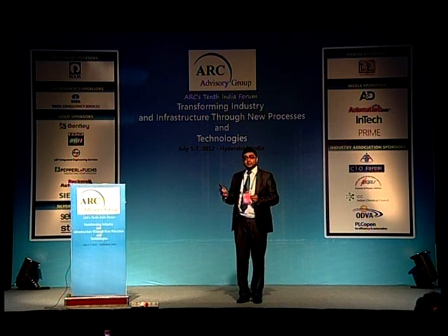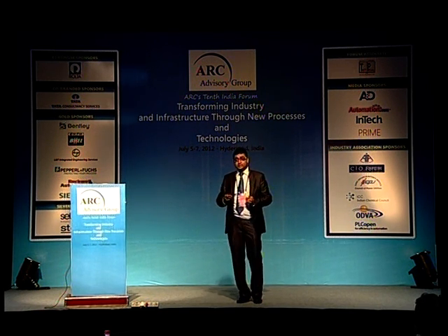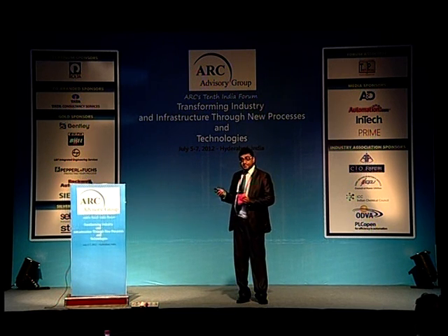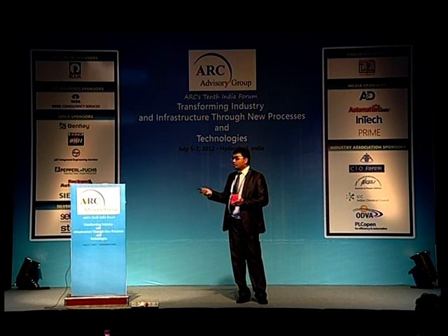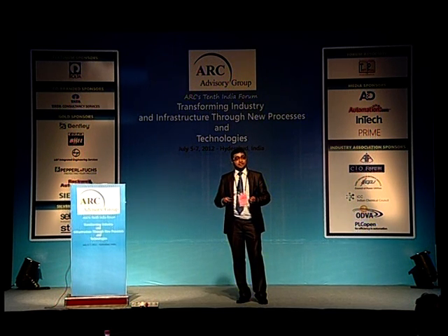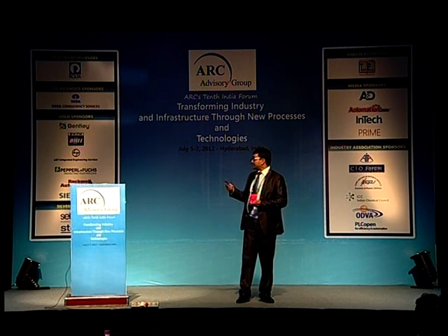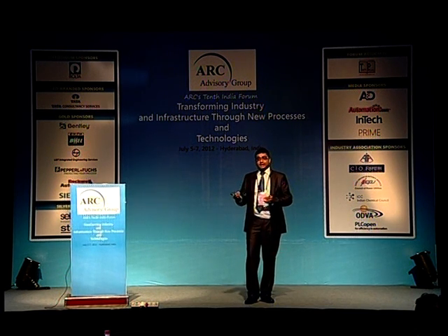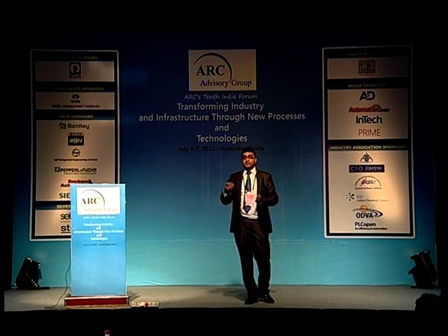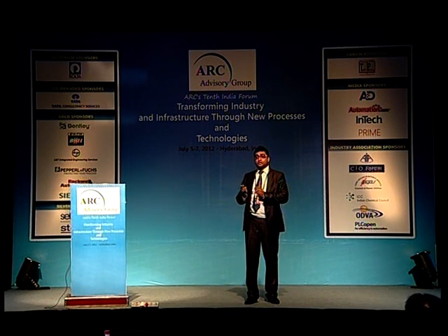How it predicts: because we have thermodynamic models, we calculate the efficiency of the fouling surfaces online from the first principle model, and then we take different process criteria. It cannot be a general solution, because every plant can have a different problem. Some plants have a metal temperature problem, some have a spray problem, some have an emissions problem. So the advantage of this system is that all operational constraints can be integrated in this soot blowing module, so that the solution provided by the system is plant specific.